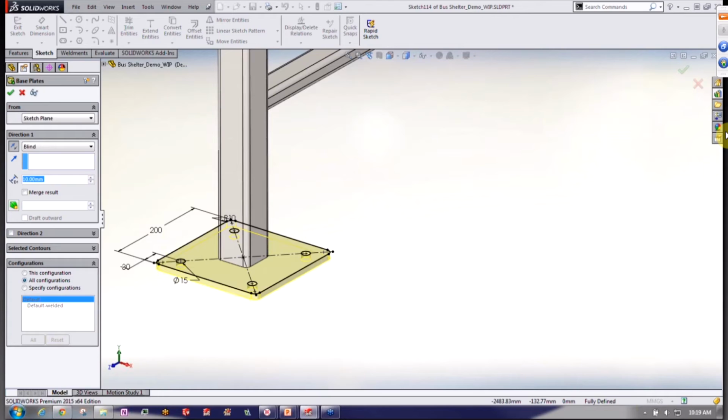Someone asked, can custom profiles be created? And yes, certainly they can. The Weldment profiles are really basically just like a sketch, just a sketch cross-section that are saved back as a library feature. So there's really not a lot of work involved with creating the Weldment profiles. And if there's certain sizes that you want that aren't included in the SOLIDWORKS libraries, but they're downloadable from, say, a manufacturer, a lot of times you can download those manufacturer's files and kind of convert those into a Weldment profile.